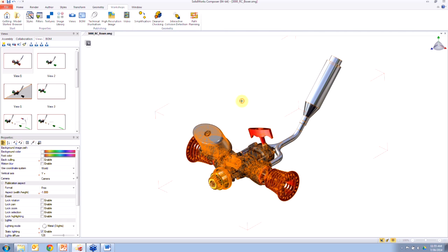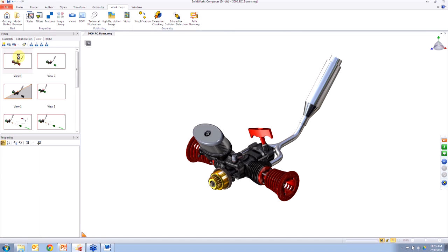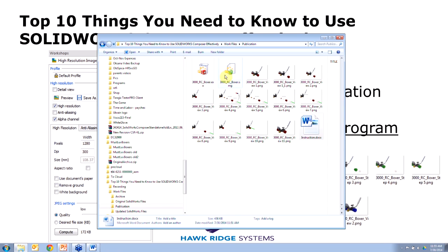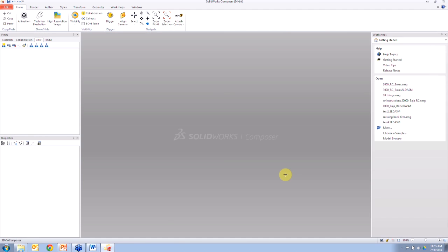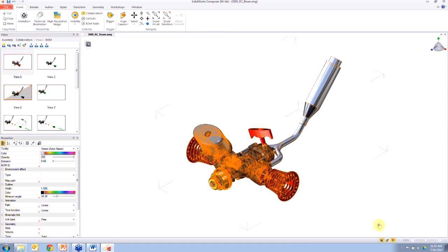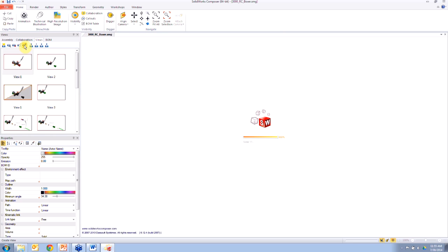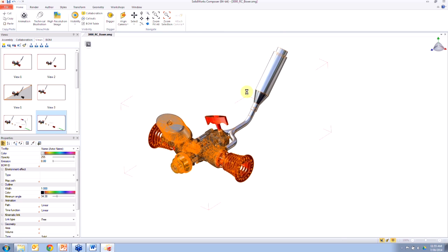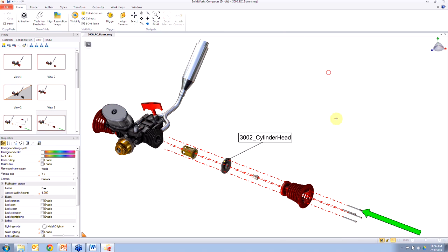Oh shoot, I forgot. You have to save the document, and you have to close it and open it. That is actually a bug in the software, and it's submitted as an SR. They're working on it, but you have to save, close, reopen for it to work. So okay, we're back to where we were. I click on it, I say set as neutral properties. Again, the golden ticket here. Set, rebuild all the views, and all the views now will have my settings that I said. The red and my Chrome and all that stuff.